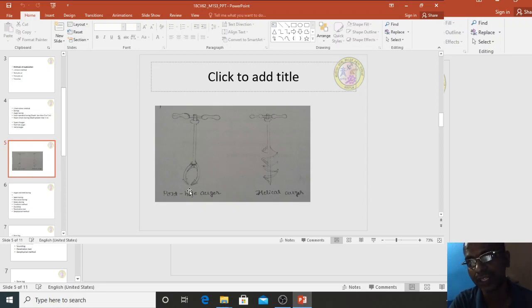If the soil strata is hard or gravelly in nature, then the cutting edge will get damaged. Then we have to go for the second category of auger, called the helical auger. The name itself indicates there is a helical spring type of coil welded to the rod. This is called a helical auger. In this spring portion the soil is collected. Not only the edge contributes to shearing of the soil, but the spring portion's toothed end also contributes to shearing. Therefore even hard soil can be sheared off by using this helical auger.